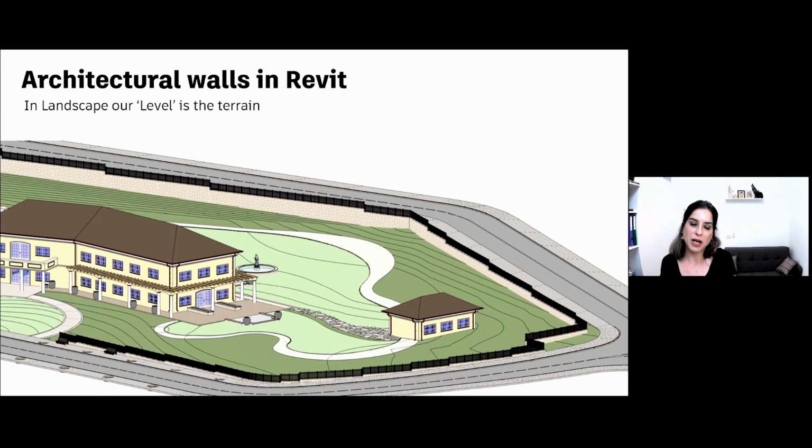And I want to show you this little situation we prepared ahead. In this situation, you can see that we have this park over here and the road over here, and we need to overcome them using the retaining wall. The regular process would be to just go to this wall over here and start dividing it into sections and then assign elevation to each section according to the elevation that I see over here and over here, and then go to 3D view and correct all my mistakes.